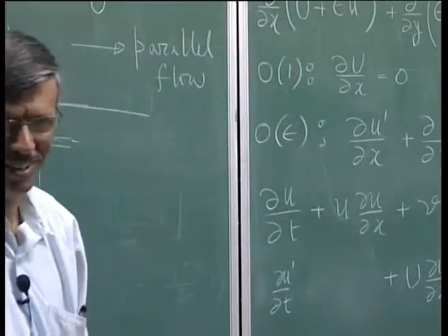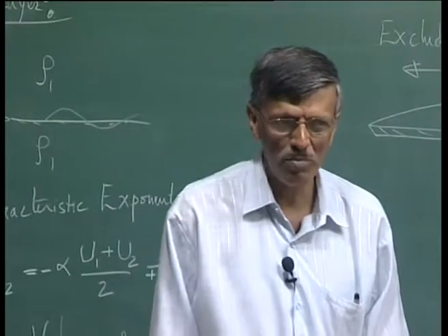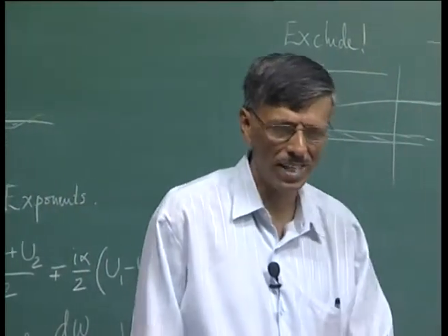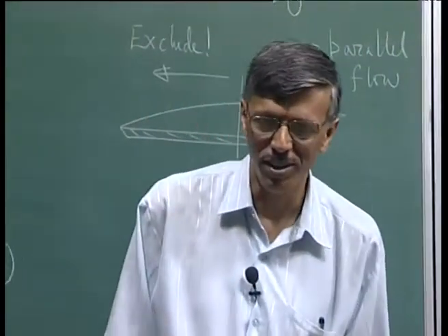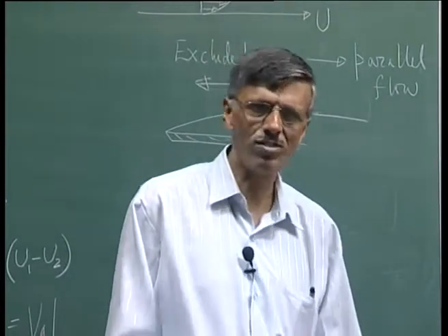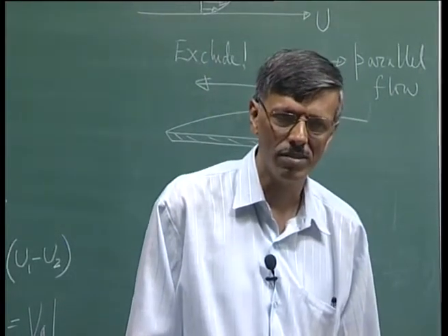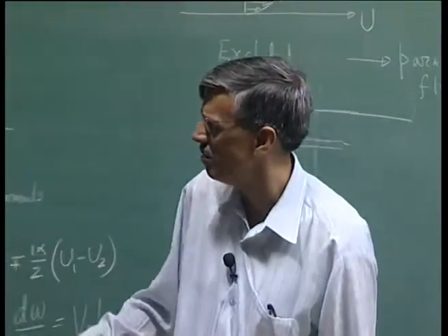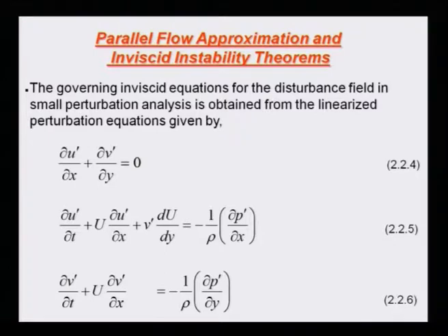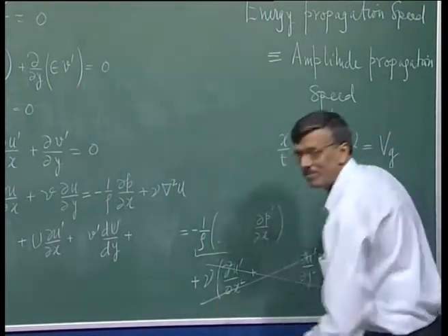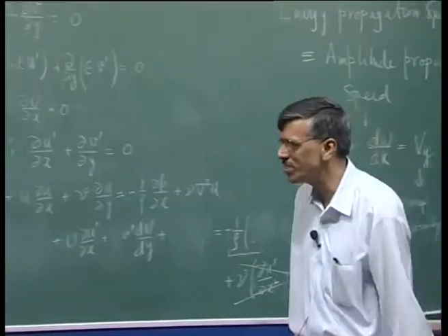Of course, this is a similar approach here, because we cannot handle the full thing, and then as an afterthought we say viscous action is there, it has to attenuate. So, let us try to find out the more critical case by dropping the viscous term altogether. That is the essence of inviscid instability. So inviscid instability would mean that we do not need to look at this term, and that is what you are seeing here.